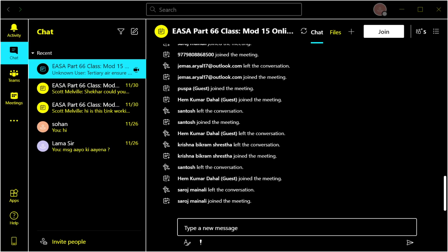Magnetic chip detectors were briefly mentioned. Again, they're a simple fit. They are push fit. You've got a valve which has a spring behind it which seals when the chip is out. But as you push the chip in, it opens the valve and you lock it in position by what's called a bayonet fix. These little pins, you push in, you twist it, pull it back, and it locks in position. The important thing there is make sure when you push it in and twist it clockwise, you pull it back because they can stick. If it sticks in the open position, you can lose oil very, very quickly. So in, twist about 90 degrees, pull back till you hear the click, job done.